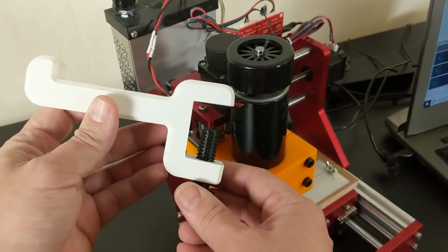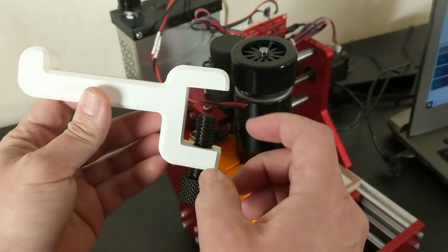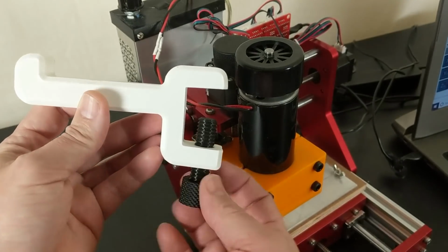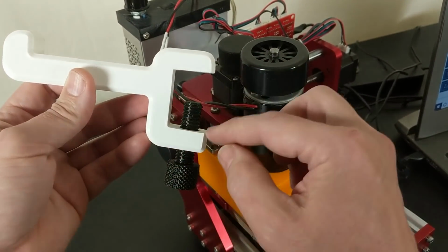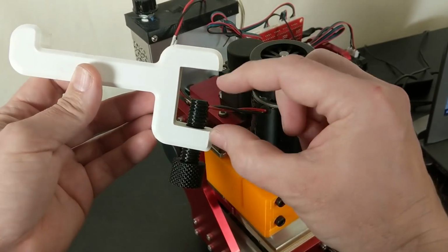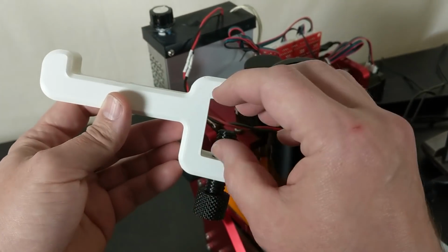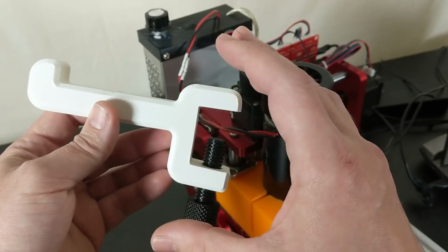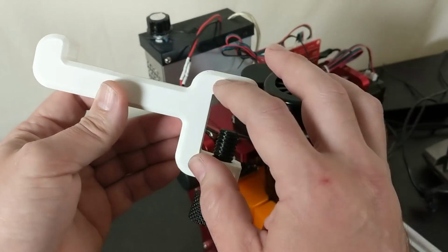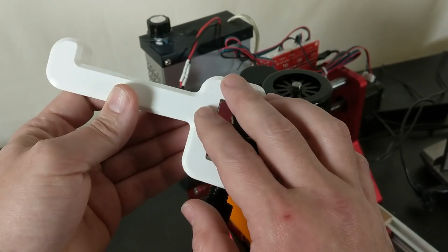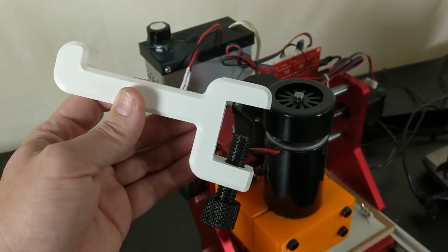Here's an example of that. So this is one of those headphone hooks that was attached to my desk for a couple of months. And when this started off life, that was not as spread open as it is. Those were parallel lines to each other. So PLA just glacially moves over time if it's under pressure. Now all plastics do this, but PLA is way worse than the others.